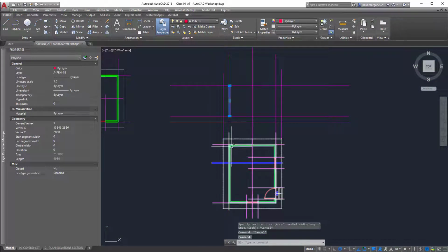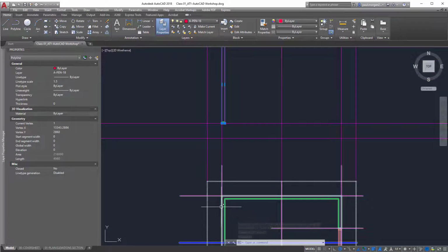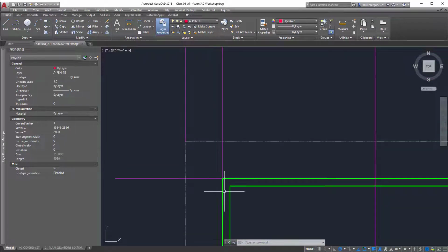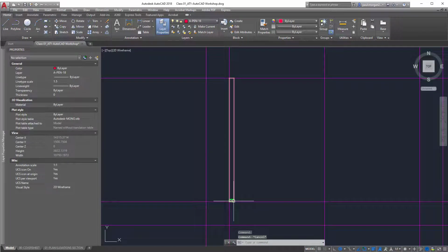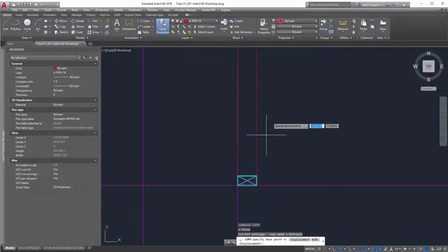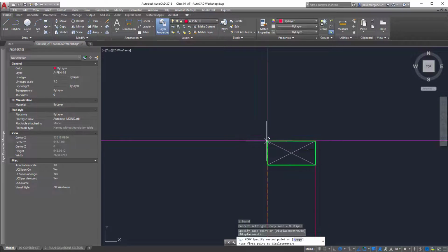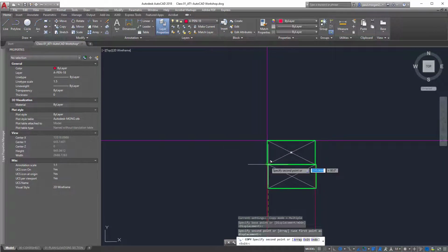Okay, so that is our stud wall on the left-hand side straight away. So we've taken it from this guideline that shows us the outside face of this wall, and then we've drawn the stud wall going up. I can then take this stud and copy this to the top. There's a double top plate on this stud wall, 1 and 2.